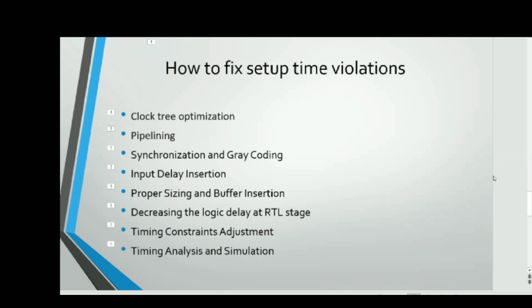It is not in a stable state, it is an undefined state. You do not know what state it will settle to. If the whole design is affected by this metastability, these types of circuits are more prone to setup violations.